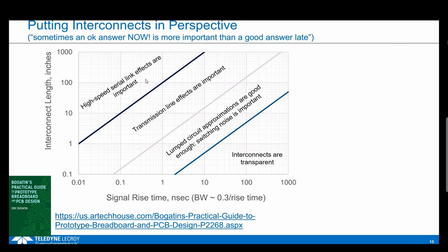This is about differential pairs and skew and length matching and glass weave fiber effect. And this is about stubs, and it's about resonant coupling, all the problems that arise in high-speed serial link type systems. They still suffer from these same effects of reflection noise and termination and routing topology. They still suffer from the switching noise problems and additional ones.